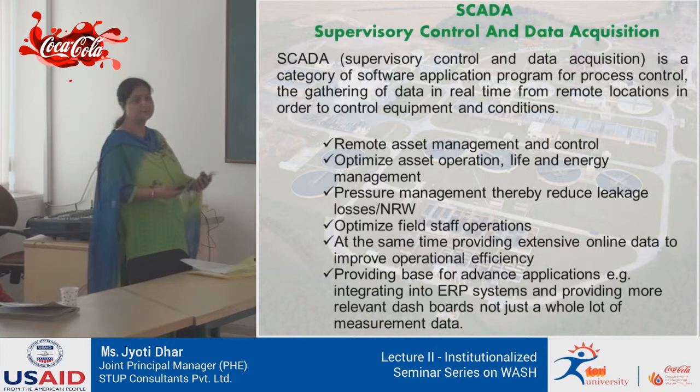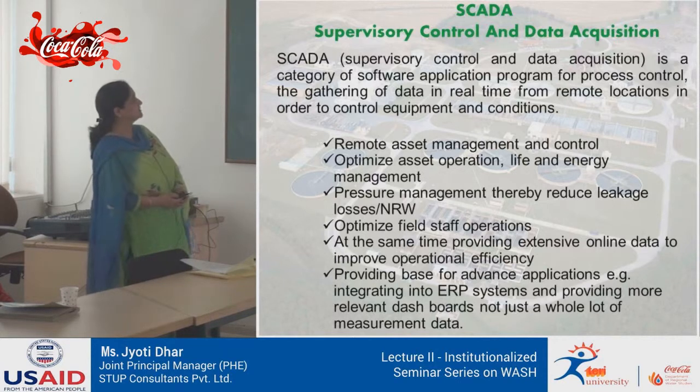Like, from a central control room, you can manage the entire plant, and you need not go to sites. You need not go to that particular area. You can control the whole plant from the central control room, and all the data is being acquired at the central control place. So SCADA is Supervisory Control and Data Acquisition, and it's a category of software application program for process control and the gathering of data in real time mode. That is, real time stamping is being done.